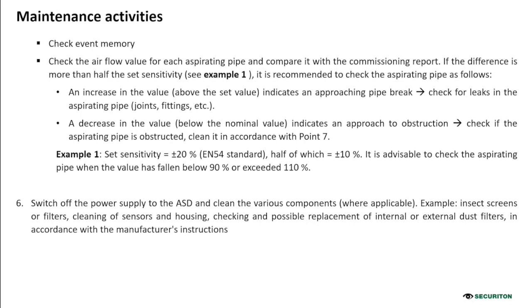Yes. The next question is, what should I do if there is no flowmeter calculation or design on a system? Yeah, that is the problem, because flowmeter calculation is very important. First, you need to ask the consultant or whoever designed the system, because you need to recover this design.